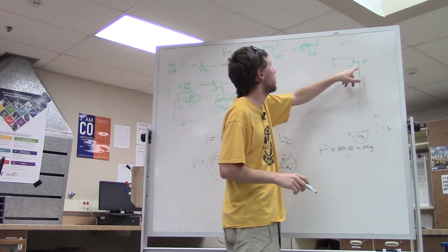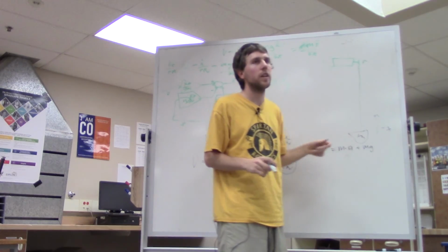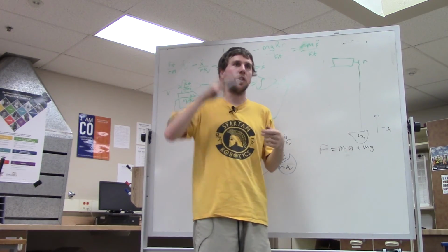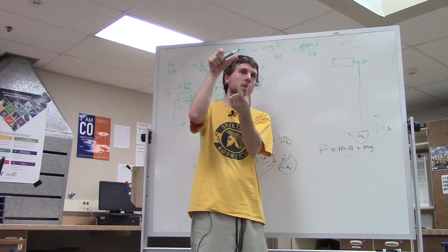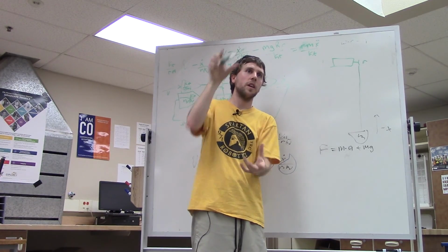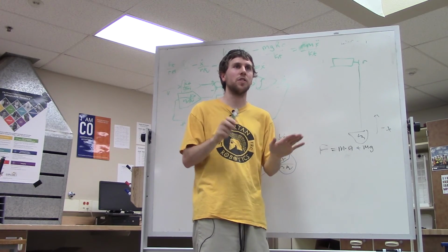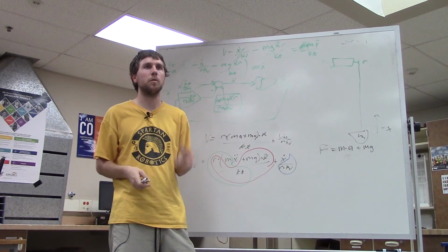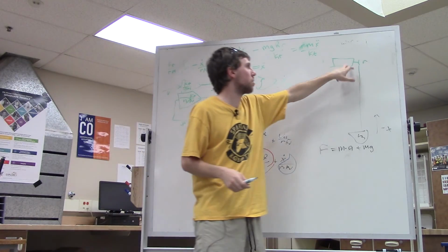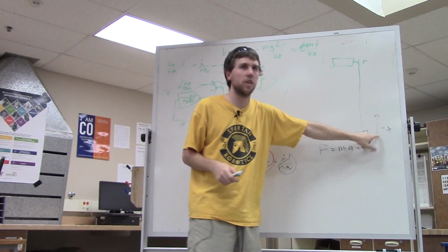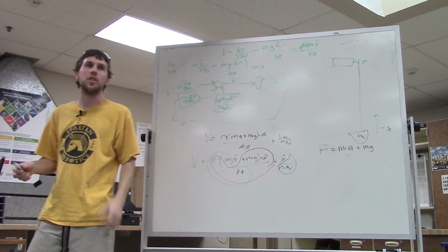The gear ratio is going to be a scalar in your torque. It's going to scale your torque up. So if you do a 10-to-1 reduction, you have a 10-to-1 lever arm on your gears. And so you'll get a 10x torque increase on your output, ignoring efficiency losses, and you will get a 10x speed reduction. So then that maps you from your angular velocity of your motor to your linear velocity. It just goes in that equation there.